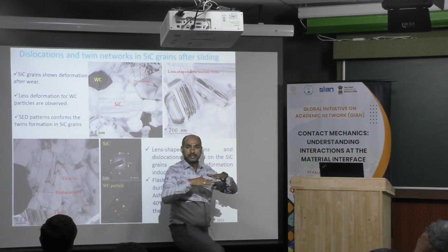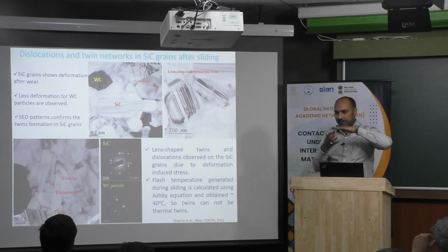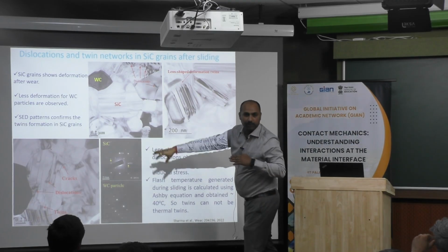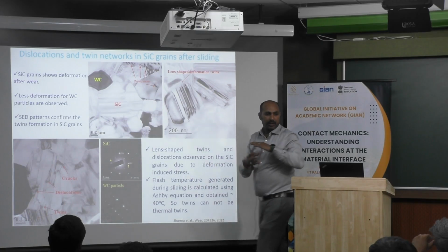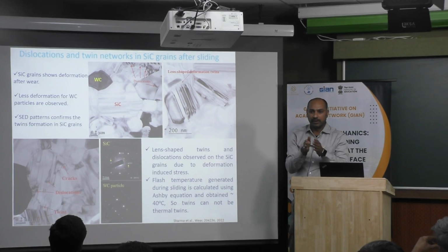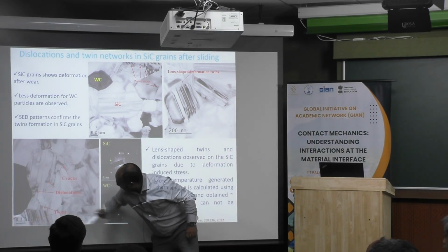So what we have seen, like Su is saying, with continuous rubbing it is getting deformed, dislocations are getting generated, they are getting piled up at any inclusion region, and then they are generating surface voids. So those cracks we can see here, you see formation of cracks.